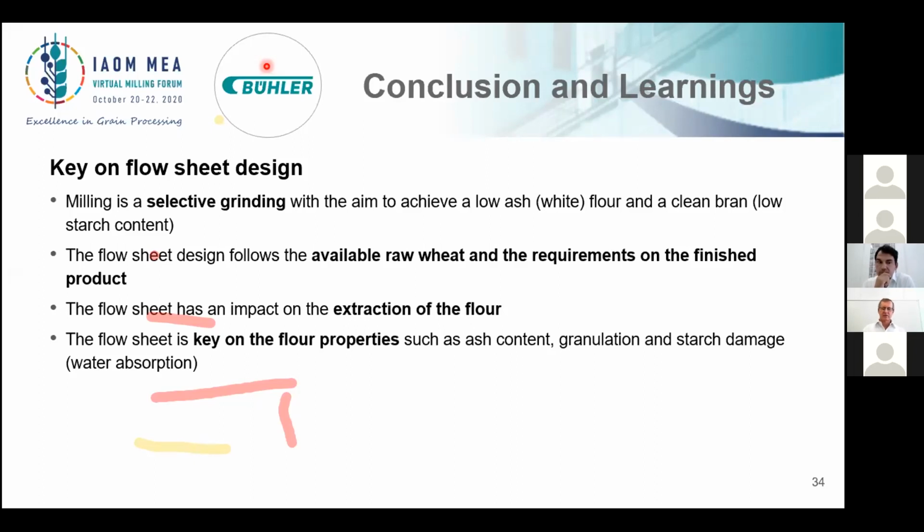So mills need to decide which way to go. It can be changed, and many millers have changed from fluted rolls to smooth rolls. If your fluted rolls are in good condition, you can make a good flour with a good gluten, but lower starch damage.